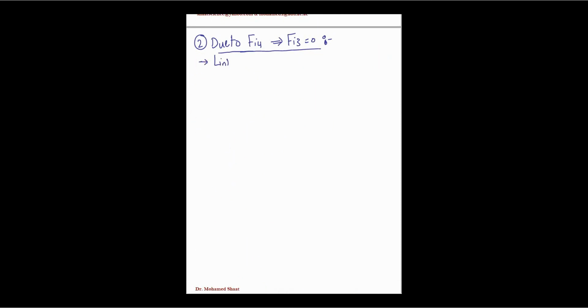Link 3 will be a two-force member. It means that there is no force polygon that is going to be drawn for this link, but link 4 will definitely be a three-force member, and we're going to have a force polygon for this member, right?